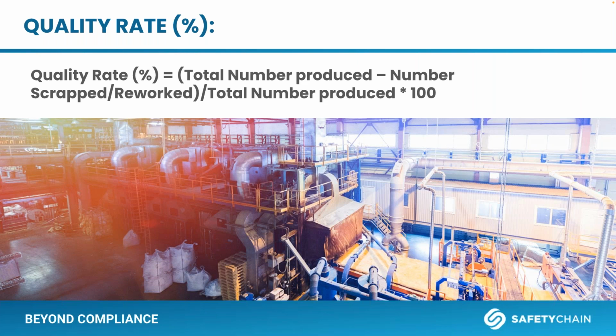Another utility, it was anything greater than 30 seconds was an outage. Anything 29.999 seconds or less was not counted as an outage. Another utility, it was 5 minutes. So anything greater than 5 minutes was an outage, and anything less than 5 minutes was not counted as an outage.